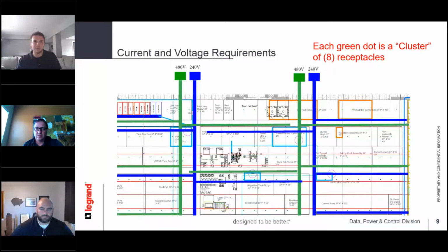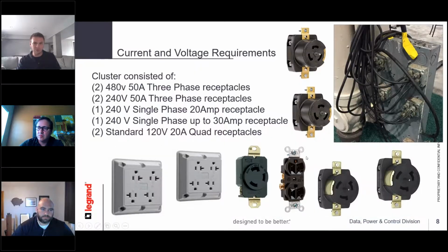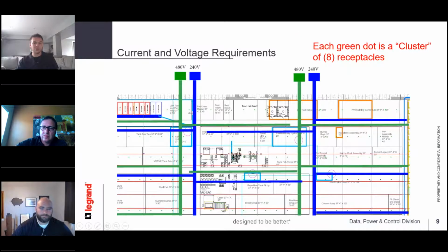As engineers, we have to take a step back and say, okay, that's maybe what's recommended, but sometimes I may know that I'm going to need more. Sometimes I know I'm going to need a lot less. In this situation, we said, okay, 65% is a good base, but we're probably going to need a little bit less because we're not going to use every one of these receptacles that you see on the screen all the time. The 6,000 amps was based on every one of these all at full load amps. So that's one solution that we were able to take from a manufacturing standpoint, look at this and say, okay, what can we do to help the end user, help the customer, help the contractor, all in one? And this was a perfect example of it here.